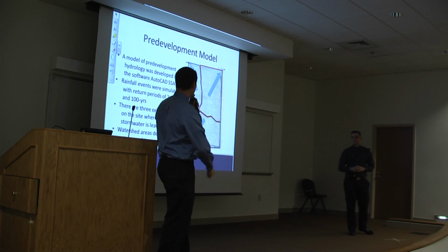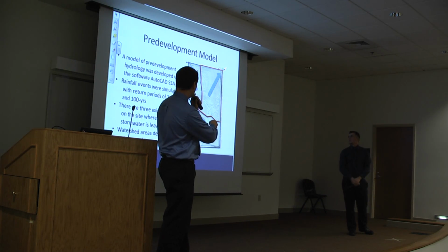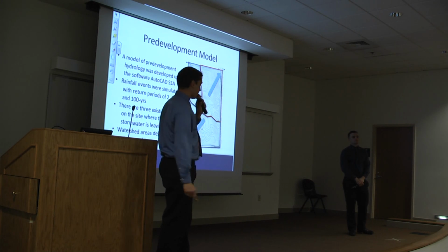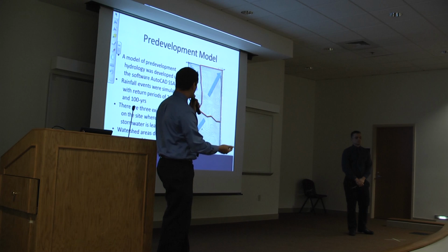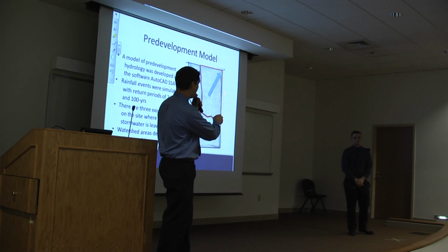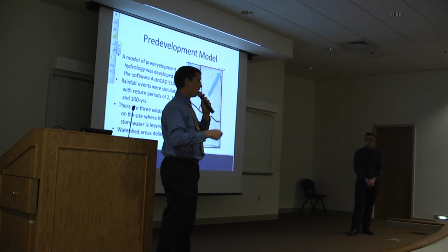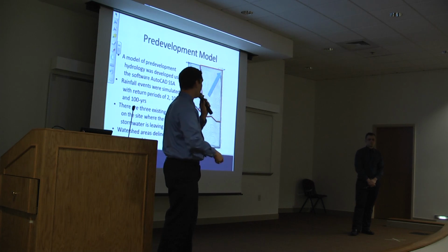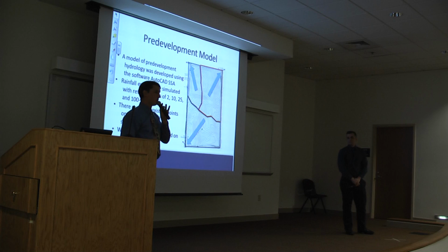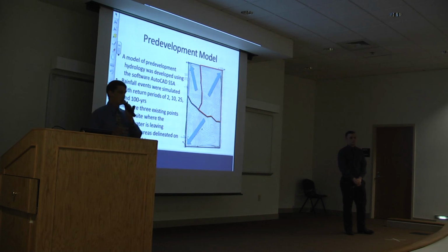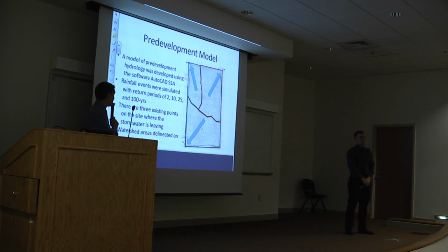They're designated by the red X showing the outfalls here, and this picture shows the watershed areas on the map. For example, all the water inside the area outlined by the red line will be flowing to this outfall. That's important to us when we're developing the stormwater criteria for the site, which I will get to later.